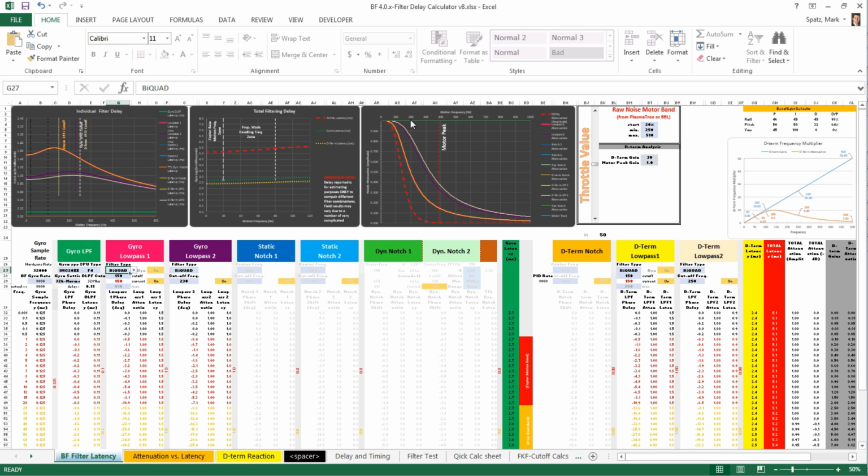You can see this is 200 hertz, this is 300 hertz, around 250s right here, and you can see we're really getting some, this is zero noise down here. This is the attenuation, or how much amplitude would be let through. So half the amplitude would be let through here, and you're getting down to below 0.1 of the amplitude. So in this filter recommendation, we're really focusing from this spot up to really just crush the noise. That's what we're really looking to do.